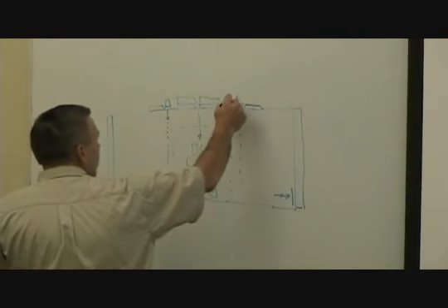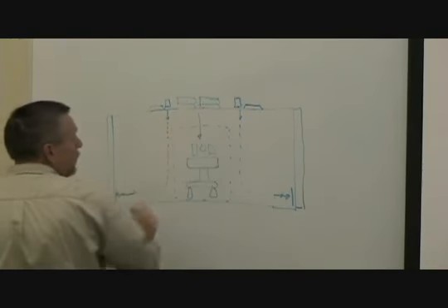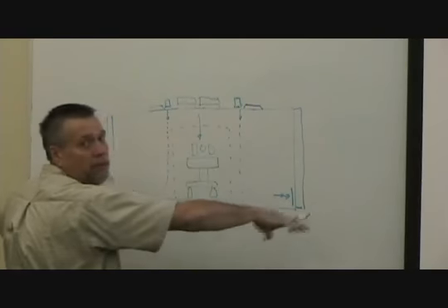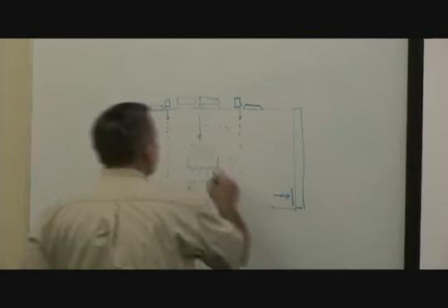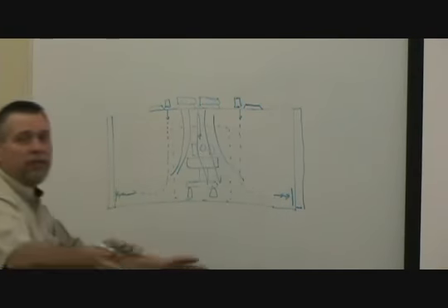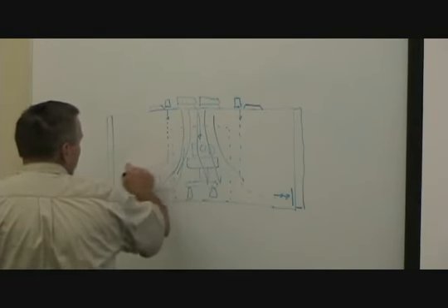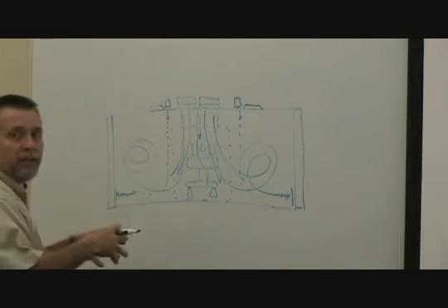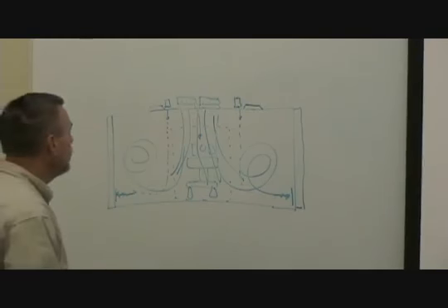So one way is just to create a perimeter curtain around the room. Another way is to use a sterile type diffuser, and it creates a piston of airflow. For the slots to a curtain, when you have these type of diffusers, you've actually got airflow like that, and that creates a piston of airflow. And what happens is any contaminants are picked up and swirled around on the outside like this and into the return. No contaminants can get into that piston of airflow because it's at 50 to 150 feet per minute discharge.